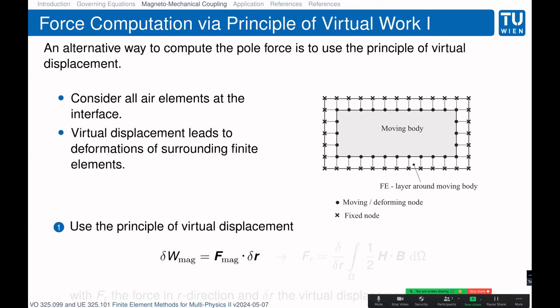So you have to integrate the volume elements, and then you see that virtual displacement leads to deformations of the surrounding finite elements, and with this you can do the variation.